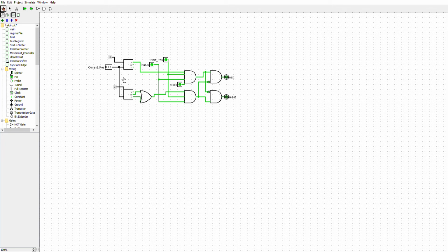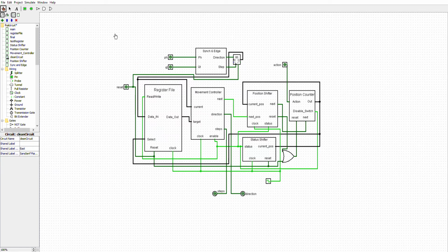And this is achieved using a double comparator circuit that detects if we hit a certain level before it chooses to reset or increment. The reason we have a double AND gate here with the NOT from one going into the other is just to prevent both of them from firing at the same time, which is just a security feature. So this is the circuit, and let's reset the simulation.